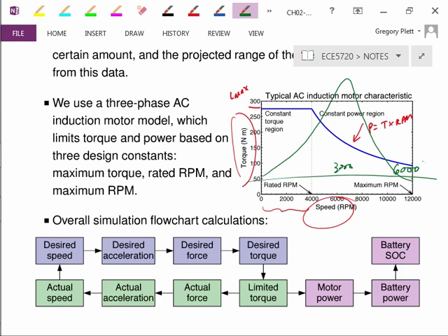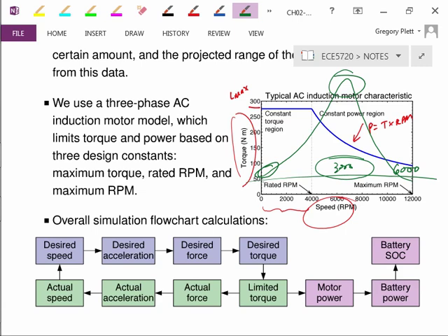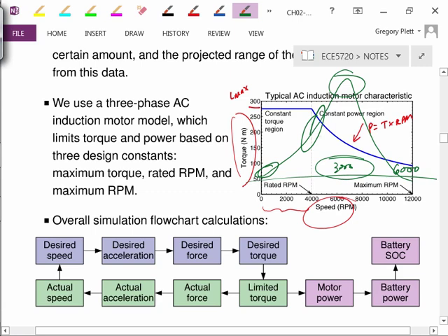This is why we have a gearbox and a transmission in the internal combustion engine, because if I didn't, I'd be operating at extremely low torques at low speeds, and I'd only get good power at high speeds. And so we use gearing to make this 3,000 RPM within the range of operation at whatever speed I'm driving the vehicle. I just gear it so that the engine is always operating somewhat close to its maximum power. At least it's operating maybe around here in the decent power range, and I can accelerate to get the maximum power if I want.